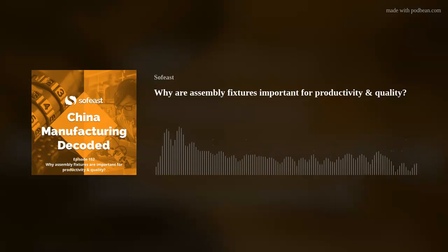Obviously, we don't want to be filling these components up with water and checking them under pressure on the assembly line. So the easiest thing to do is fill them up with air. And once you've got an airtight system, you can check very simply on a pressure gauge with a needle whether that is holding air or whether we've got a leak somewhere.